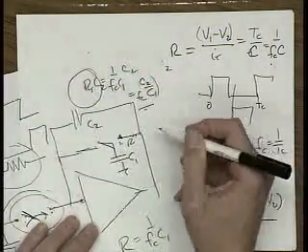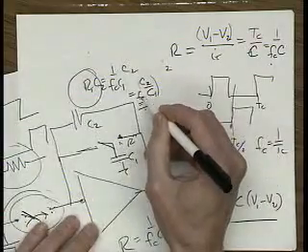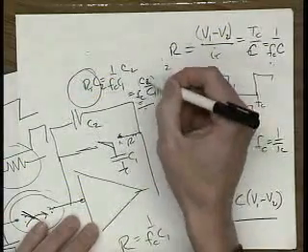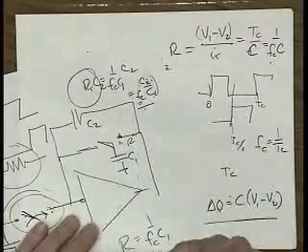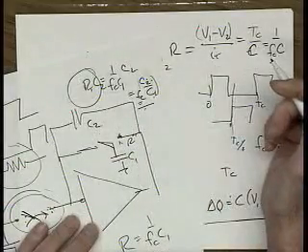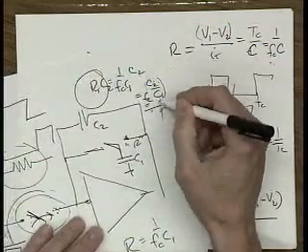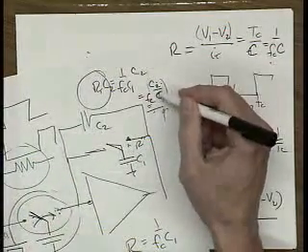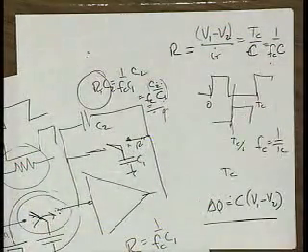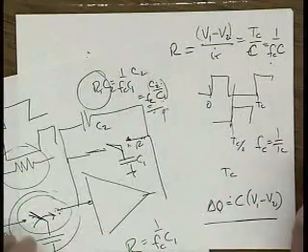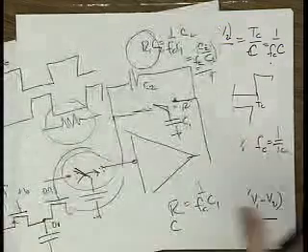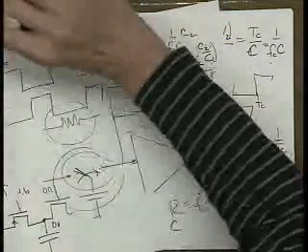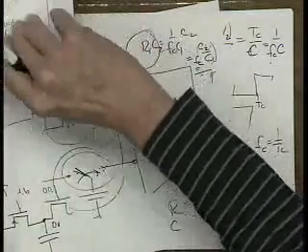Wow, that's pretty neat. We can set the clock frequency, we can set the ratio of these two capacitors, and we can get precise time constants. It doesn't need a huge capacitor. The area is very small, actually, because these capacitors are only ratioed. We don't have to make them big because there's no absolute value concerned. This whole idea here is based on switched capacitor filters. So you can build this thing up and you can do all sorts of fancy circuits. I have a picture of one here.